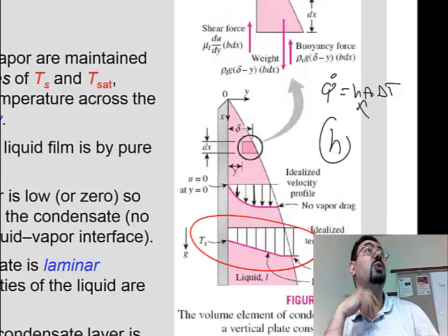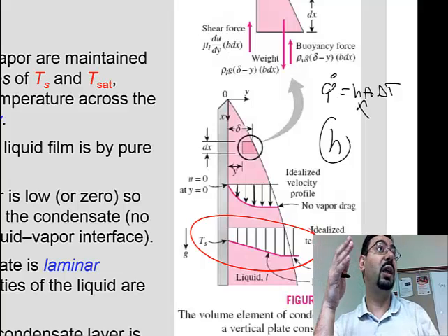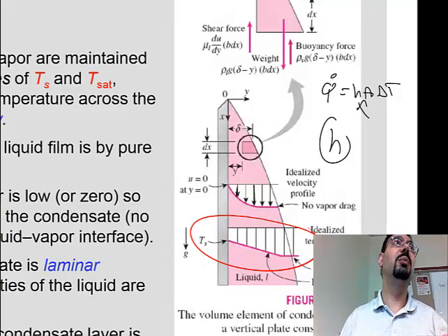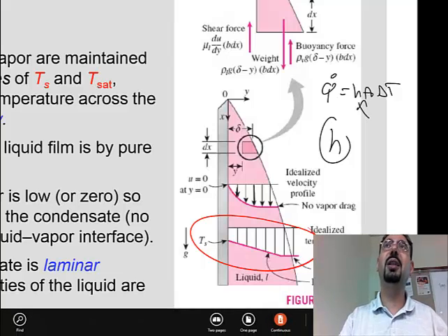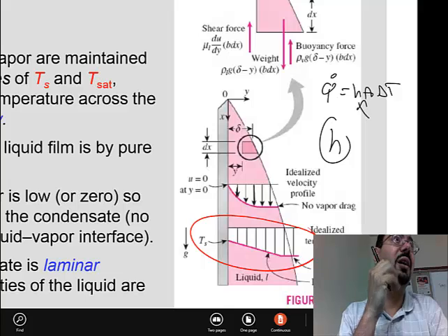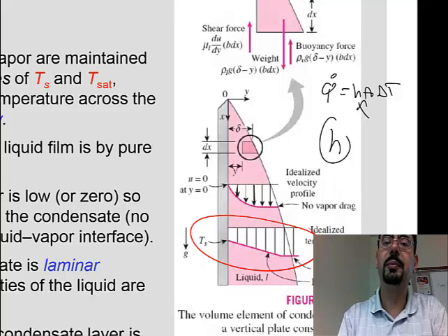So when we say that the Nusselt number is H L over K, that's basically relabeling the problem. It's like when I ask how much you got on this exam, and you tell me, well, it's a letter grade. So what is a letter grade? Did you get A, B, or C? When I ask how you calculate the H, you say, well, let's calculate the Nusselt. Well, it's just putting it next to a K and D, but still we didn't calculate the H. How do you calculate the H? What do you think?